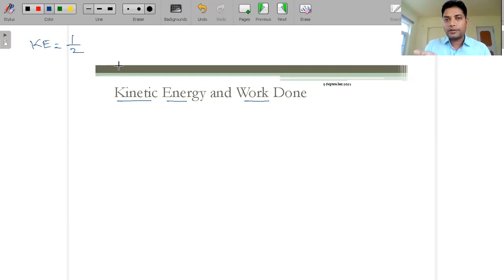So mass is of what? Here the pressure energy is converted into kinetic energy, but this kinetic energy is retained by what? It is retained by the abrasive particles, because abrasive particles are the only ones moving with a very high velocity, and because of that only the material is removed. So this mass will be of the grit, so this is mg, please keep in mind.